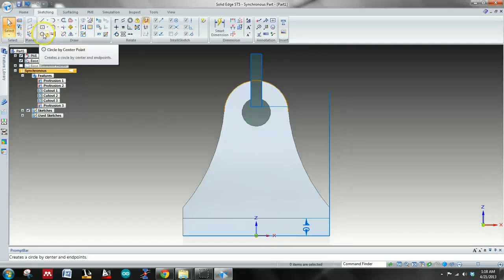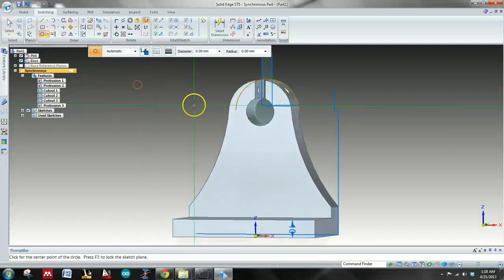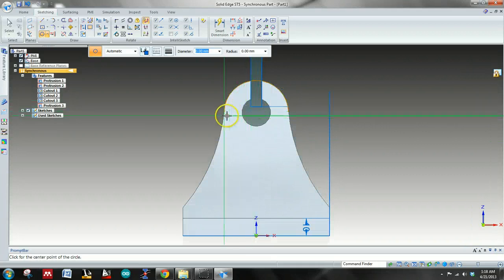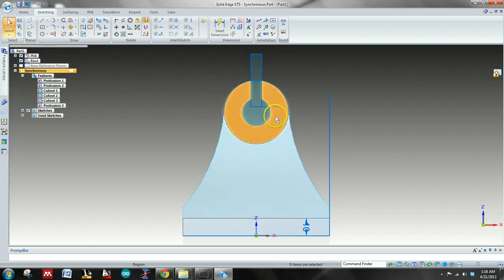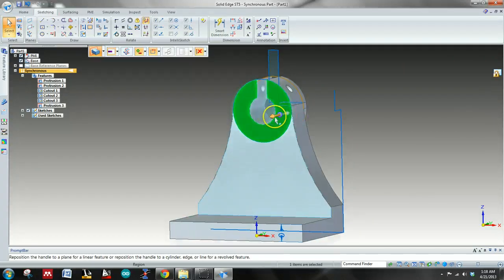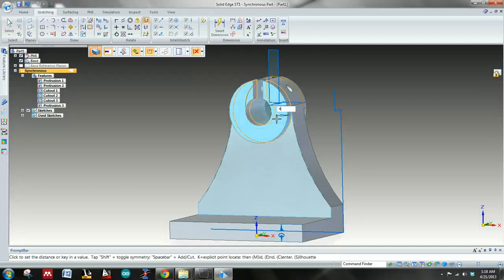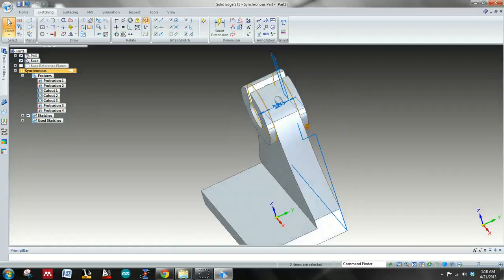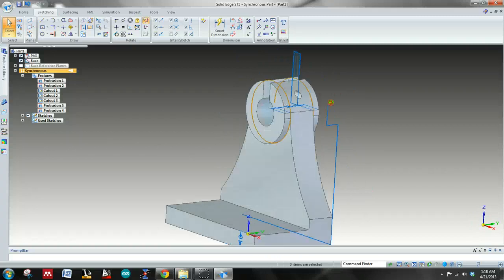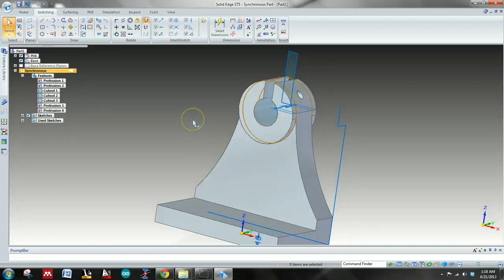And we want to, so we're on the front side here, so I'm going to just skew this just a little bit, hover over top, F3, Control F. Yeah. And we want to make another circle, so center point, click, bring out to the edge because we know that that's solid, 36, enter. Okay, so same thing like we did on the back side, hover over top of the region we want to extrude, click, pull over so we can see this, come out, 4 millimeters. Wonderful. So we added 4 millimeters on either side of that, and that is good.